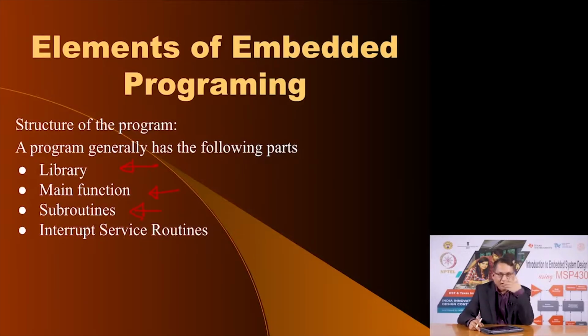And if you are an embedded programmer, what would distinguish you from conventional programmers is that you are going to include something called interrupt service routines. They are also subroutines, except they will be invoked once when some event happens. That event could be you press a button, or the event could be you receive a value from the serial port, or the event could be that an internal timer reaches some value and so on and so forth, which we are going to cover in subsequent lectures when we talk about these peripheral features. But you are going to be adding interrupt service subroutines into the C program.